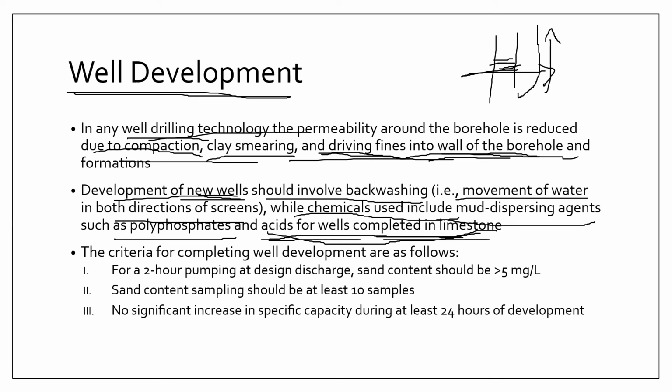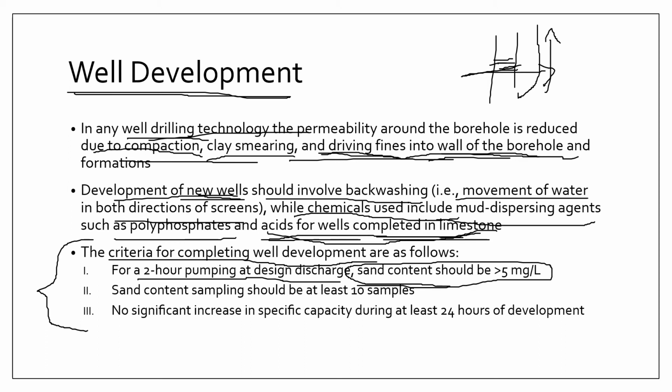And then finally, the criteria for determining whether your well development has succeeded is as follows. You should do a 2-hour pumping at your design discharge, and at that pumping rate, the sand content should be less than 5 milligrams per liter.